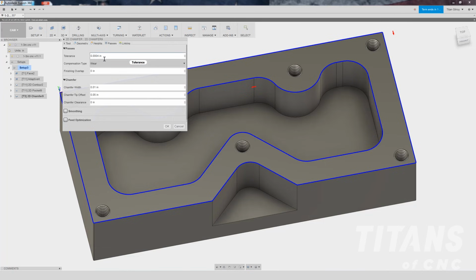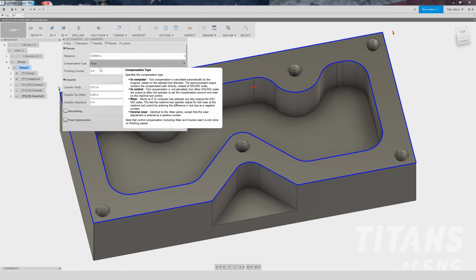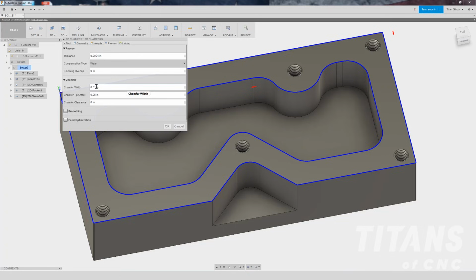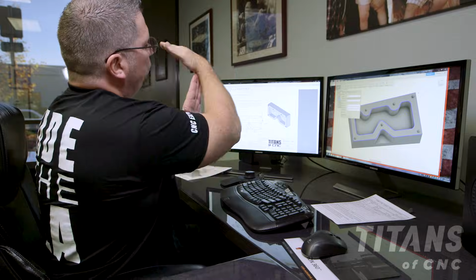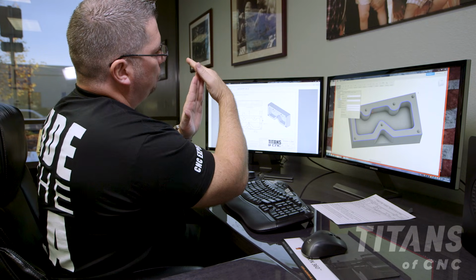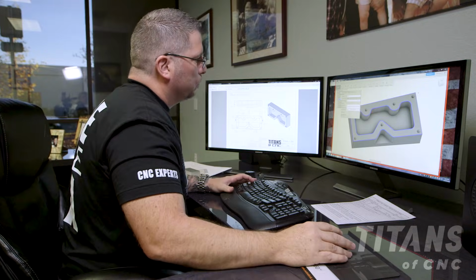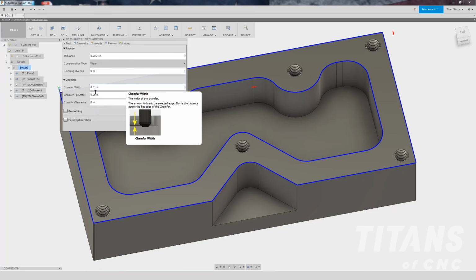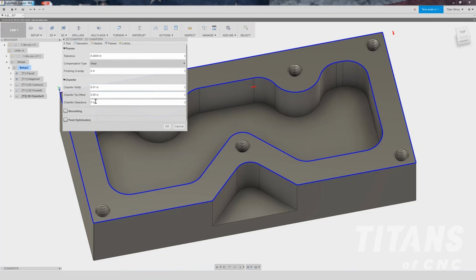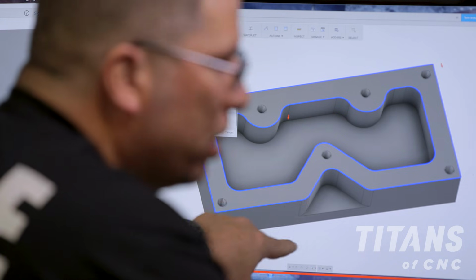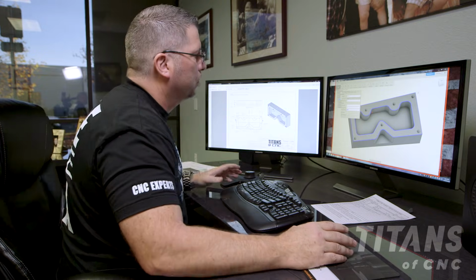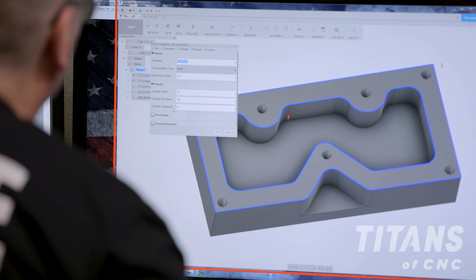I'm going to put wear, so I have my G41 line. I'm going to come down to my chamfer width. The chamfer that I'm putting on the edge is going to be 10 thousandths. My tip offset is going to be 0.05. So it's a 45, so it comes off 50, drops down 50, and then anything beyond that will be your chamfer depth. So 50 thousandths. The clearance right here doesn't matter on the top because I'm not going to hit anything, but once I drop down here, I'll use it so I don't hit that edge. So right here, I'm just going to say 0.